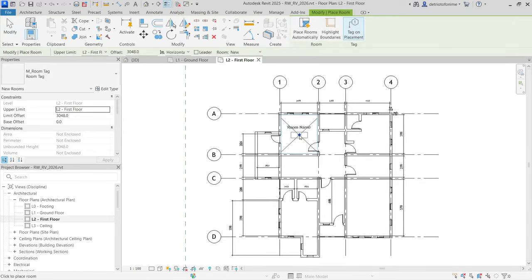And then if you go into an empty space that is combined like this, a space that is completely surrounded by walls is going to have a room. If you go and click a place like this, it has to be surrounded by walls. If it's a place that is not surrounded by walls, you can't really have a room assigned to those places. So let's just start with the very first room here. Just go ahead and click. It's going to give you room 1.